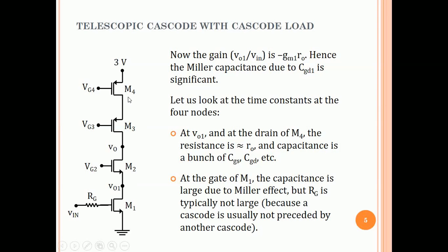This looking up is GM RO squared. So you'll get RO2 plus GM RO squared divided by 1 plus GM RO. So it is approximately GM RO squared by GM RO, which is RO. So the resistance at this node is basically RO by 2 actually. I've said RO, so the order of RO.